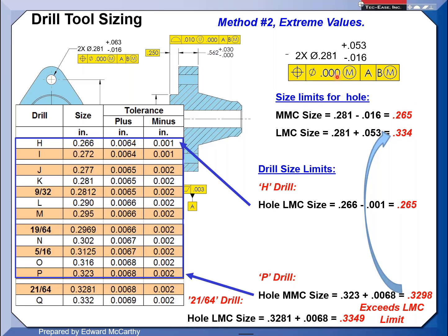And now my manufacturing engineer, if he knows this, can come up here and look at the size of this hole, what we did here. Originally it was minus 1 plus 7 thousandths, so we only had a total of 8. Look at this, it's huge. I can do this with a hand drill now.